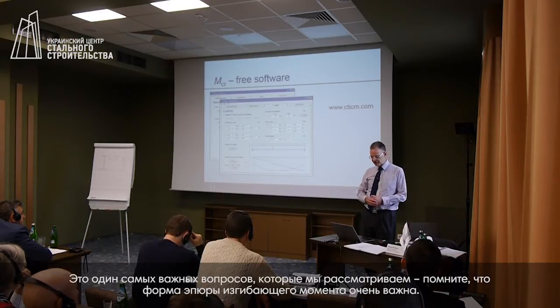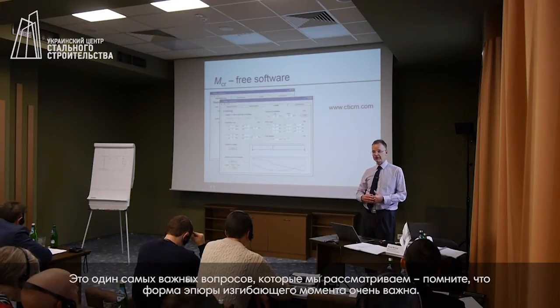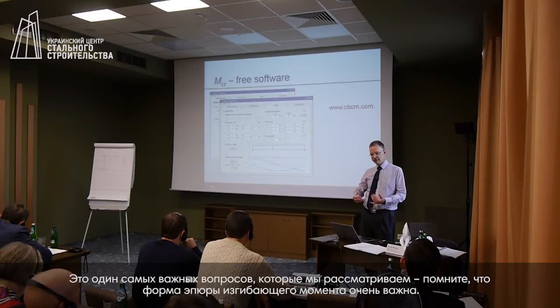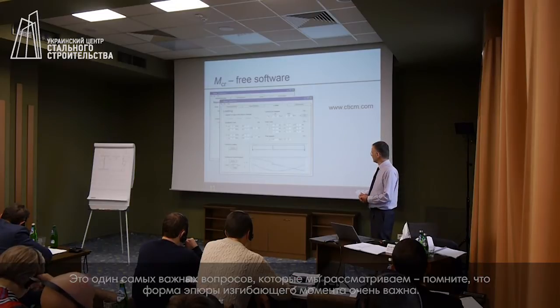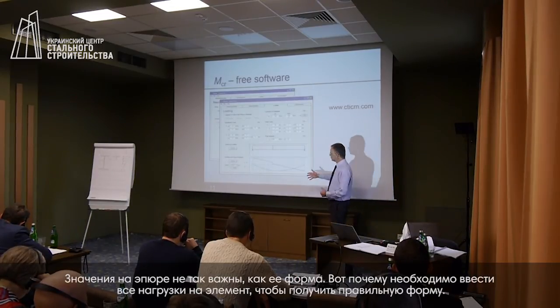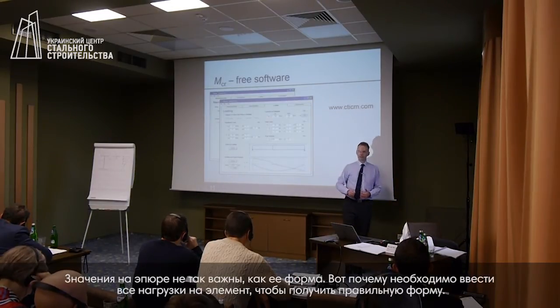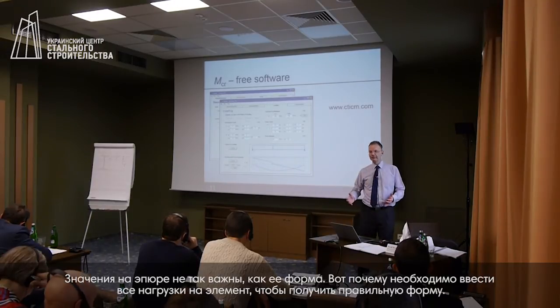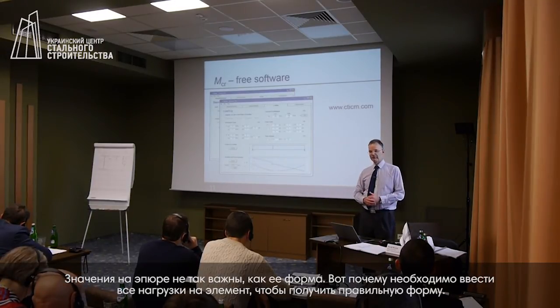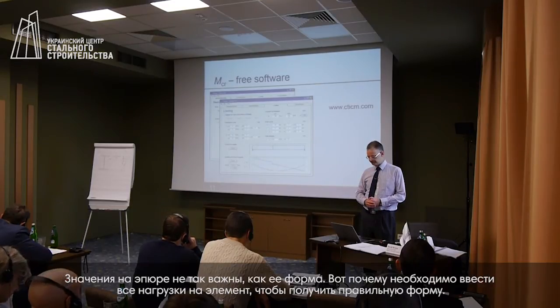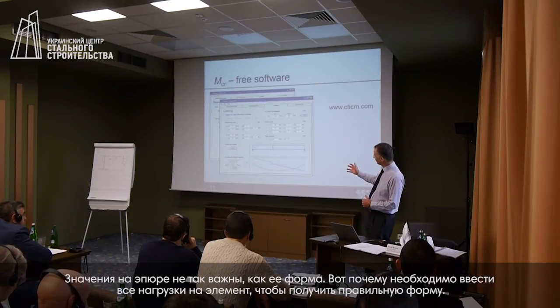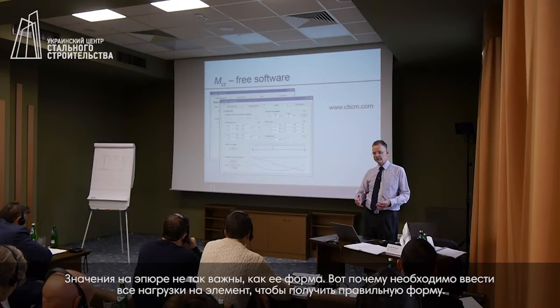So one of the important themes for me this morning is that you must be concerned about the shape of the bending moment diagram. The overall value of the bending moment diagram does not matter, but the shape of the bending moment diagram is of critical importance. That's why in the software we enter the loads to get the right shape of the bending moment diagram.